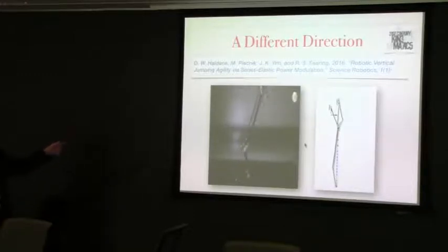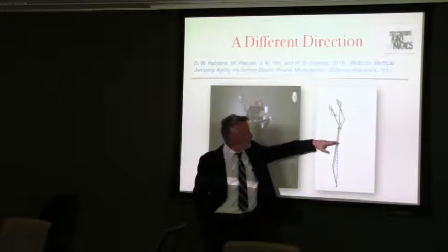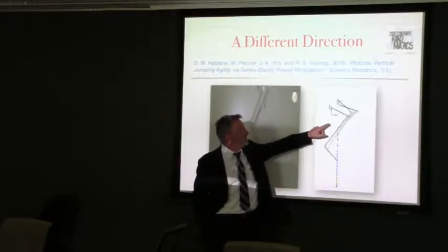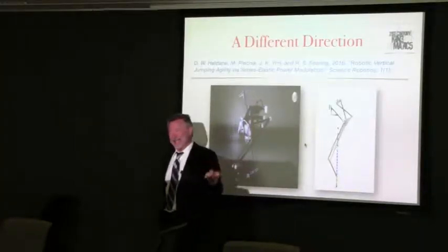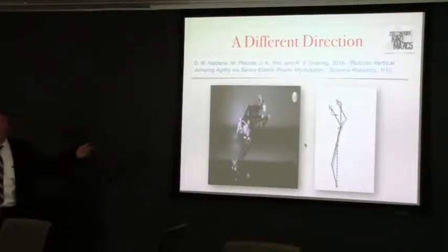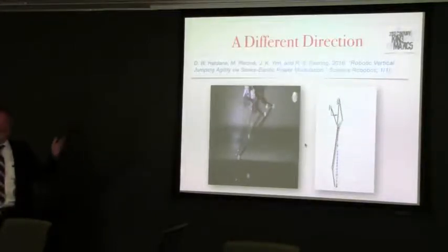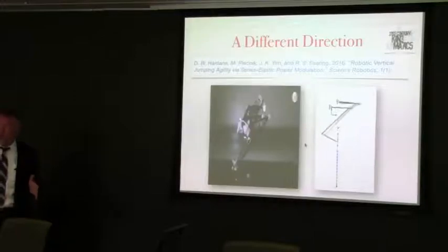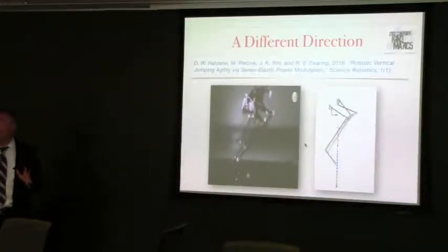What you can see here is that he's programming the velocity at these various points and then designing the 6-bar linkage. Because this 6-bar linkage has the same topology as the original one that we ran the 300 hours of computation on, we can use the same solution and just use a parameter homotopy to explore these other designs.